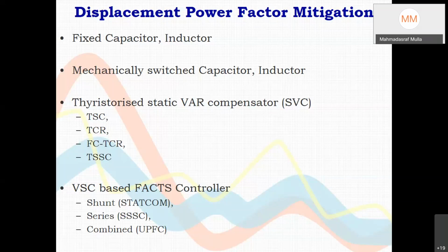So the energy storage you require is not at 50 hertz. So you don't require large capacitor, large reactor. So with an SVC based arrangement, with a smaller inductor and smaller capacitor, we can do the same job. Here you don't require that large reactor and capacitor.